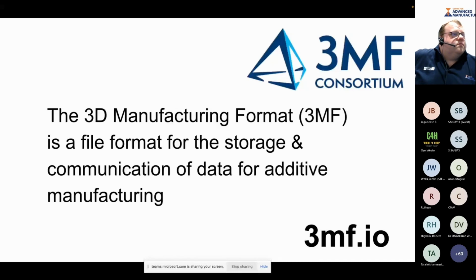Okay, so although this is definitely an improvement on STL, it does seem to show that most industrials still prefer BREP CAD. STL and 3MF lose the model's B-rep definition, the crucial modeling designs. Yeah, if you can use the BREP data, then use BREP data. So the 3MF format is here for situations where you can't use the native CAD format. I'm not saying that it's the answer to every situation, it's the answer to situations where CAD and STL do not work.